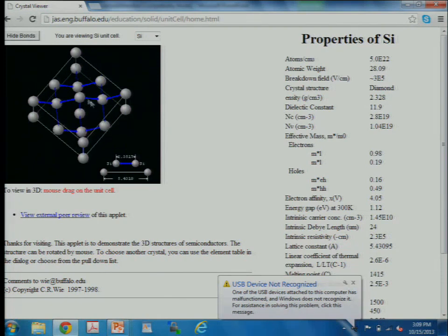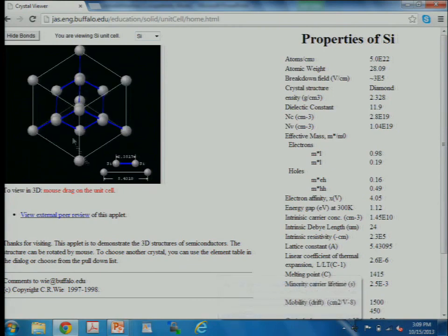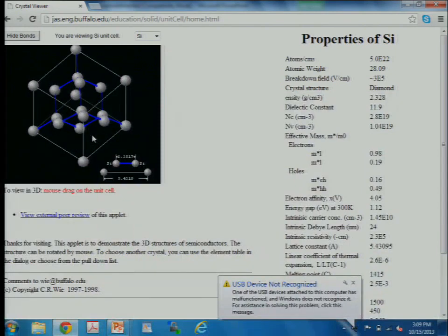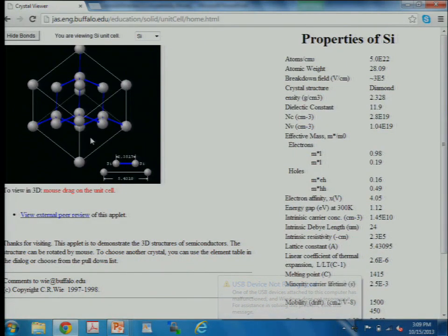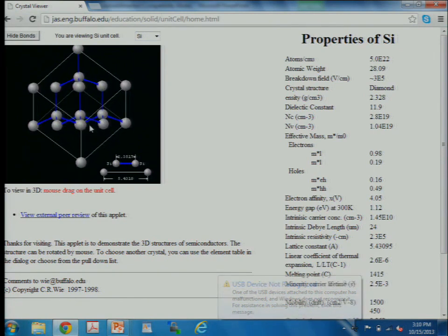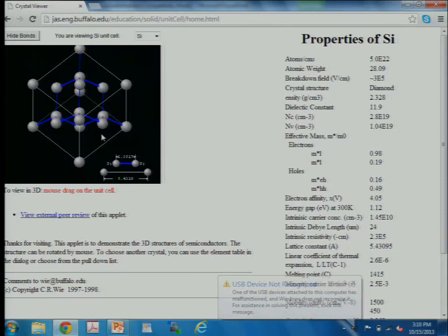Now if we look at a 111 direction, let me find, okay, so this atom right here, it actually does have some bonds sticking out of the plane, but let's look at this atom back here, and let's say this atom here was removed. Okay, so now this atom back here will have one dangling bond, but it will have three covalent bonds holding it in place in the silicon. So that's kind of what I want to show you.